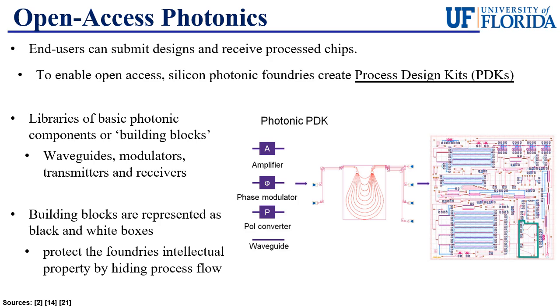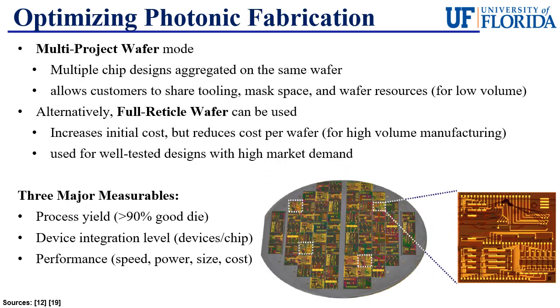Designers can also design their own building blocks to go into these PDKs that follow the design and fabrication rules of the foundry to better push the limits of these devices. Some limitations that are set by the foundries may be the minimum isolation between components, the maximum wafer depths, or the maximum feature sizes.